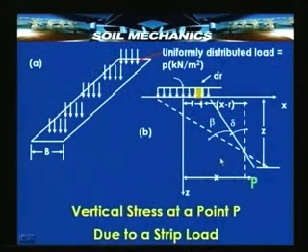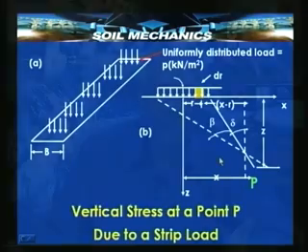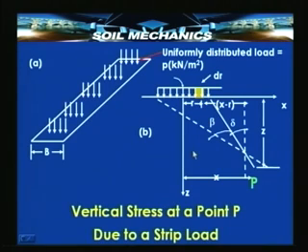This means that if we need to determine stresses at any point deeper than this, or any point whose z non-dimensionalized with respect to b by 2 is larger than 2.5 or the x dimension is larger than 3 when non-dimensionalized, we need to go back to the actual formula, substitute appropriate values and get the results. If you remember, we had also seen another diagram, a cross sectional diagram which illustrates the angles beta and delta which are to be used in employing the formula that we have for stresses beneath a strip load. So, either the formula or the table can be used for computing the stress.